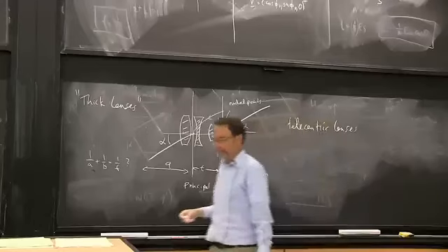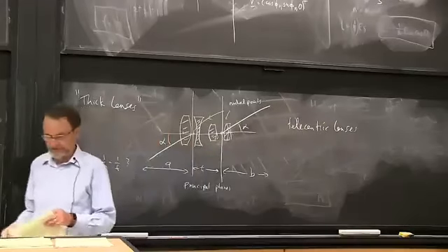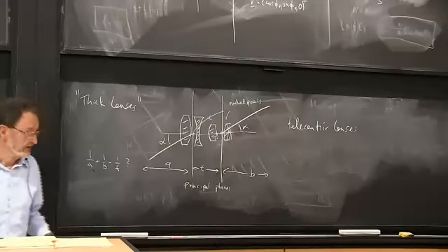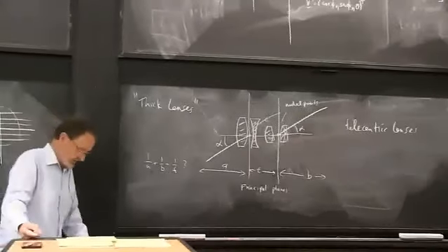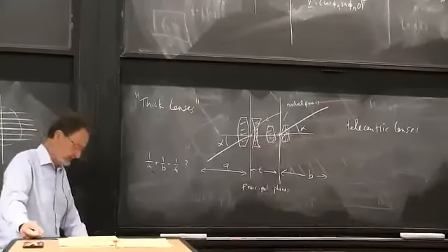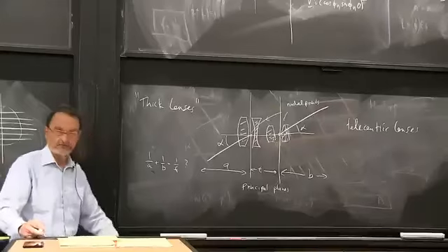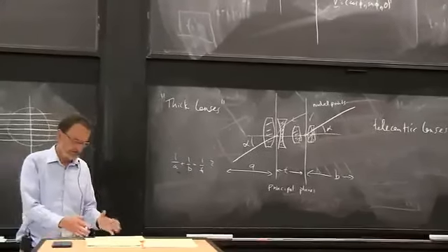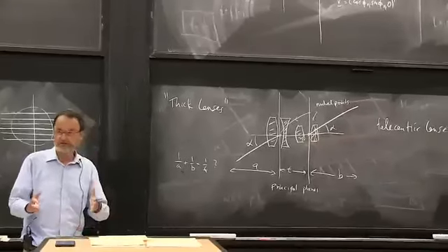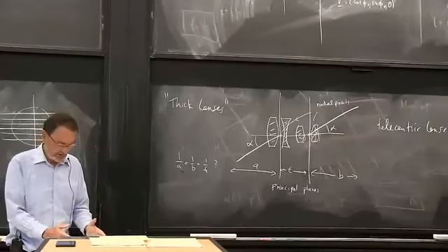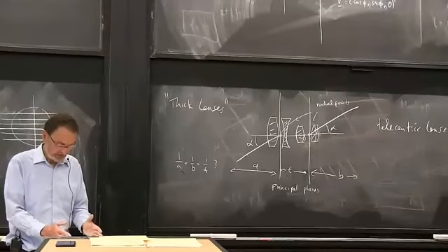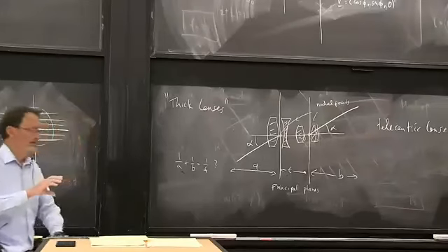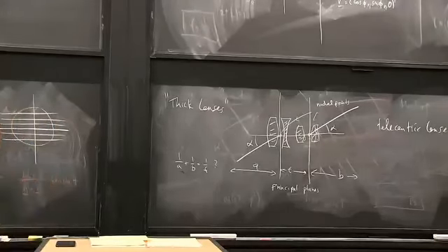Why? Well, there are a couple of reasons. One is that when we have perspective projection, the magnification changes with distance. So if you say looking down at a conveyor belt and reading labels and whatever, or trying to make a precise measurement of some dimension, well, the image size will depend on focal length and the distance to the object, and if there's any variation in the distance to the object, that's problematic.